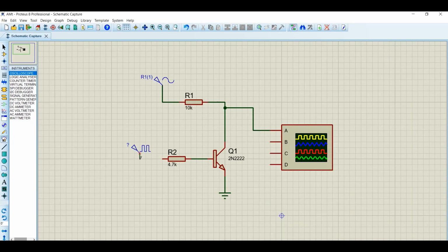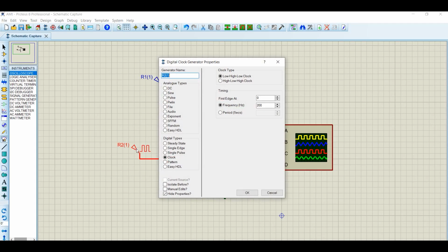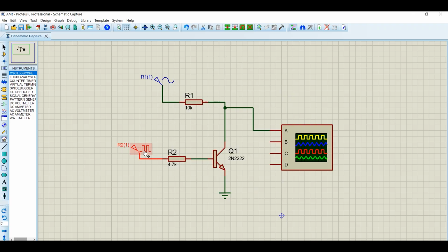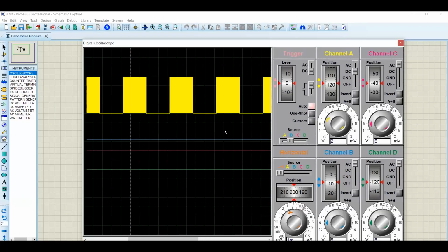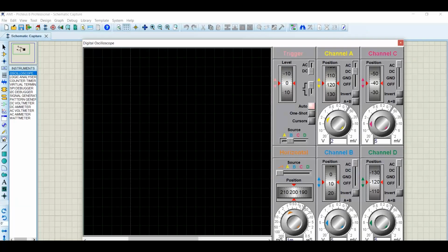But if you apply a square wave signal, which could be a digital message signal like the output from Arduino pins or temperature sensors, to the transistor's base, the carrier signal at the output changes shape. This type of modulation is called ASK, and it's very simple. Check out the output waveform.